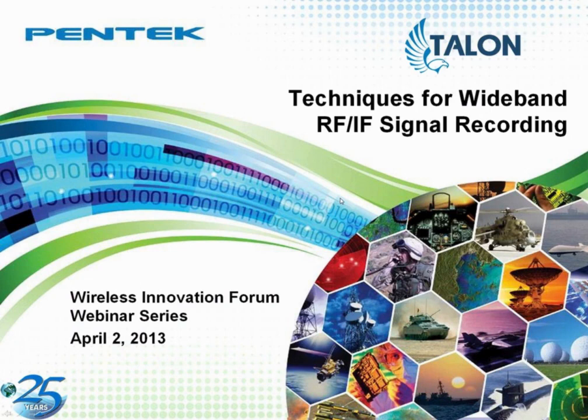We then go through another mixer and local oscillator using digital technology to translate the baseband digital signals up to IF digital signals, intermediate frequency, which then go through a D to A converter to analog IF, and then through an analog RF up converter to produce an analog RF signal that can be sent through a power amplifier to the antenna. So again, it's just the reverse, very similar operations, but done in the reverse direction.